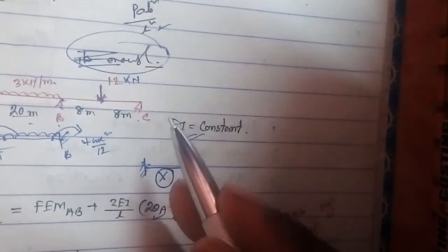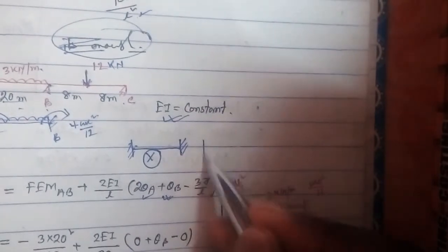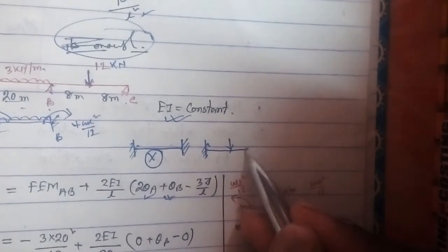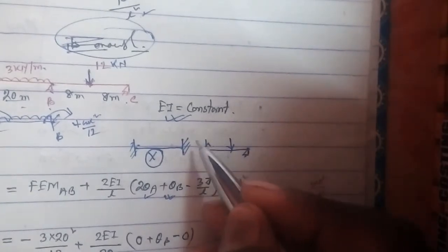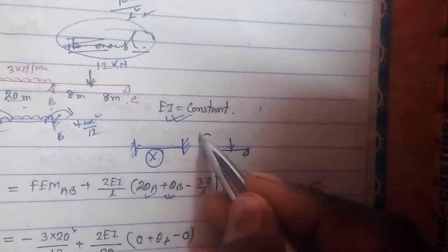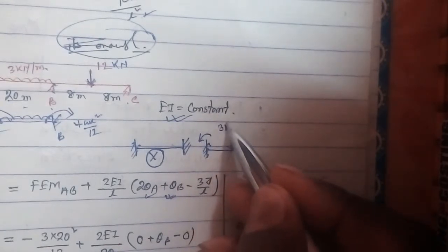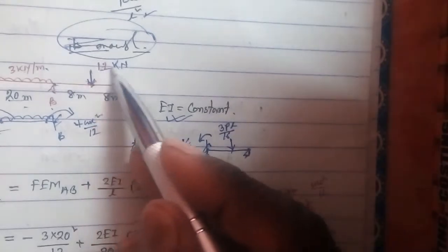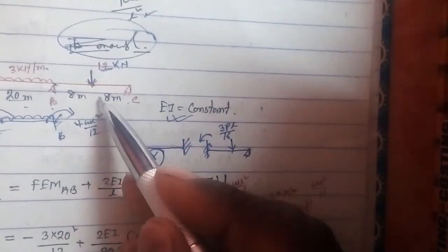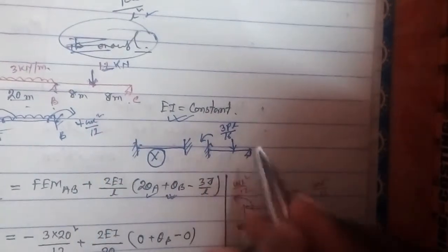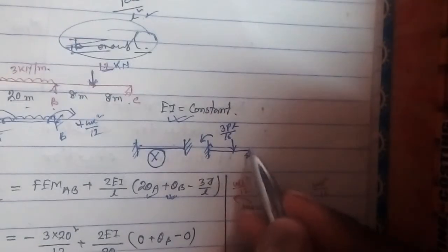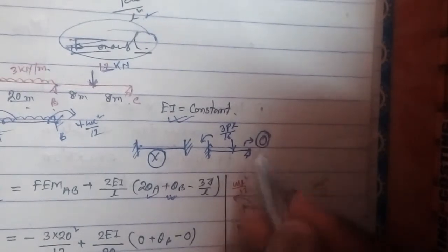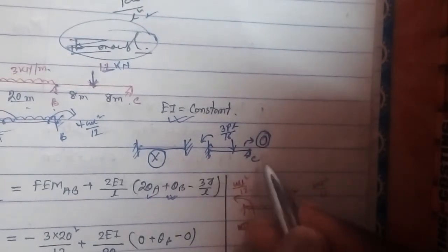What we will do here is fix one end, and the point load is acting here, the hinge support is here, and we know that this fixed end moment will be 3PL by 16. Here P is 12 and L is 16. So we have to put this in, and at this point the moment will be 0. Fixed end moment at the point C will be 0.